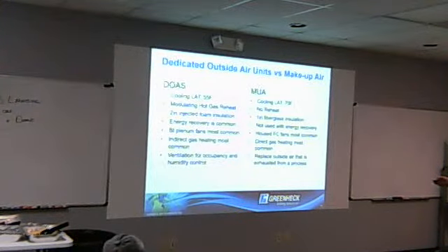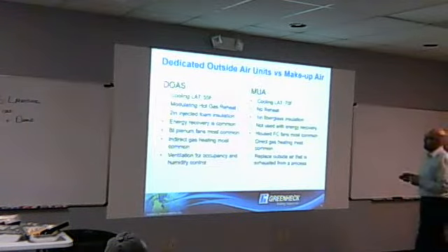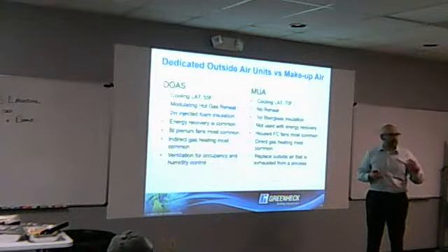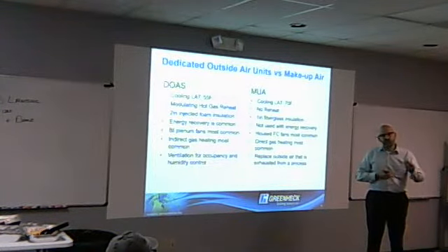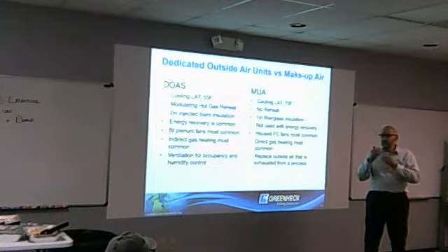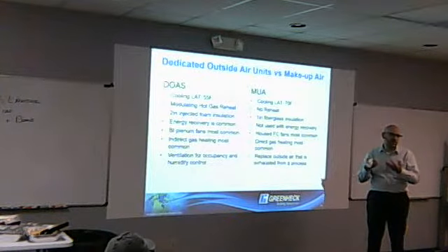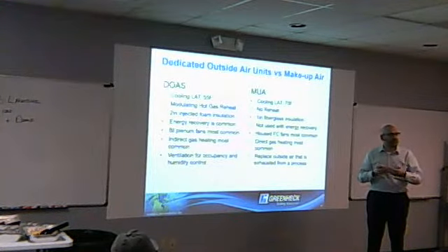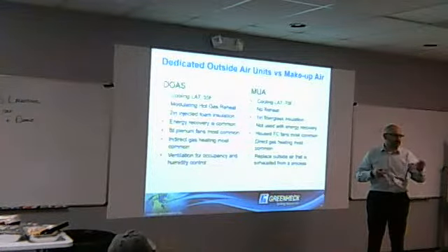2-inch injected foam to improve the thermal resistance of the cabinet. 1-inch fiberglass. Again, neutral air. We're not adding that much energy to do cooling, so we don't have to worry as much about that. So we bring that down. Energy recovery is common. This is outside air coming in because we're taking air out. We've already heated and cooled that air from the space. We put in an energy recovery wheel. Now we can further reduce that load from the outside air just by recovering that energy. Normally we do an energy wheel. We could also do an energy core. And most of the time those are total energy, so it's an enthalpy core, not just sensible handling.